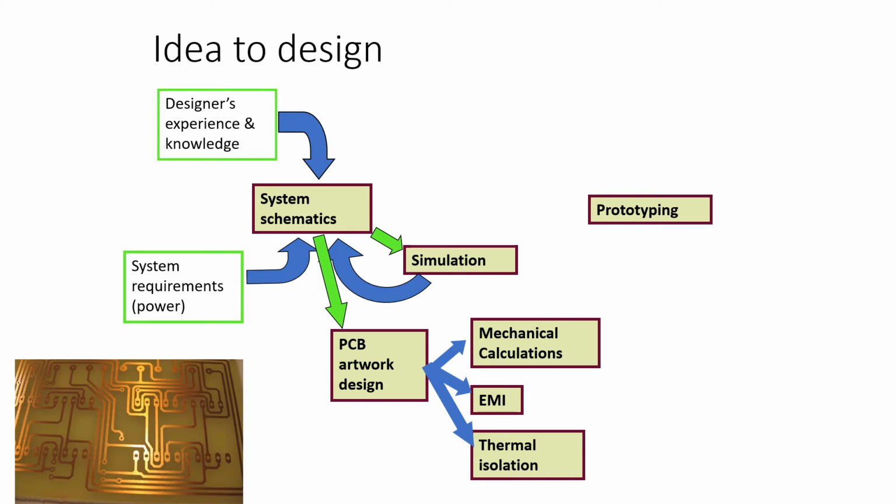So internal electromagnetic interference could be very large. In that case, in the design, of course, you can think of different mechanisms to have Faraday cage like structures so that you can isolate certain areas with ground. So those are the things that you need to do.